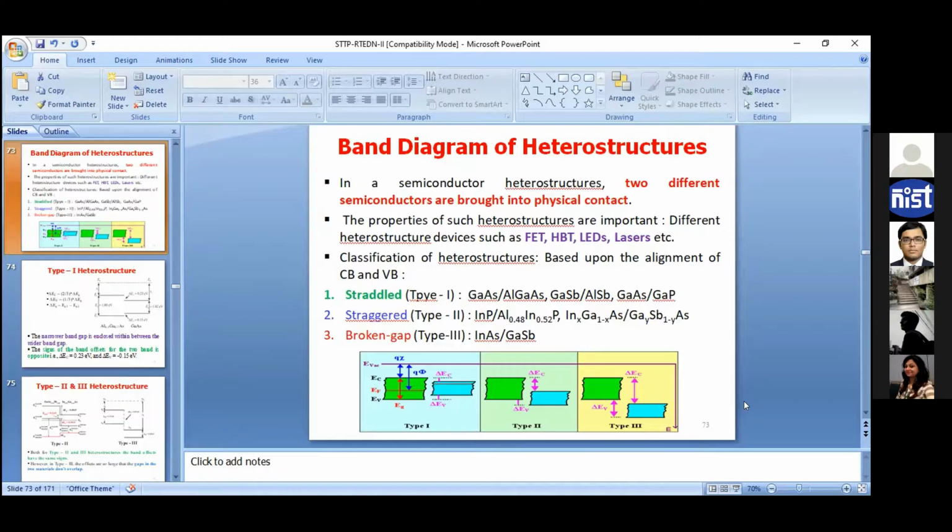As we make it more and more narrow, the band gap of the graphene nanoribbon will increase. But when we are asking for a contact with a bulk semiconductor, that depends on the size of graphene, as already mentioned. A graphene and semiconductor contact is a different thing, and sometimes it is very tricky because graphene is ambipolar. If you make any contact, graphene gets doped. For that reason, that particular junction needs to be specially taken care of.